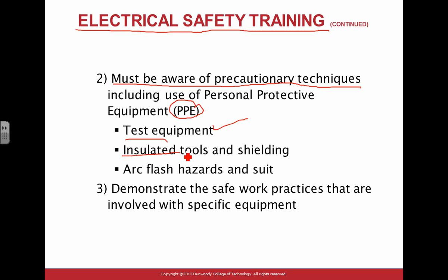Okay, then we talk about insulated tools and shielding. You will never ever, guys, approach a piece of equipment when you work on it energized. And again, we'll talk about energized: when you work energized, you work with energized objects, voltage rated.